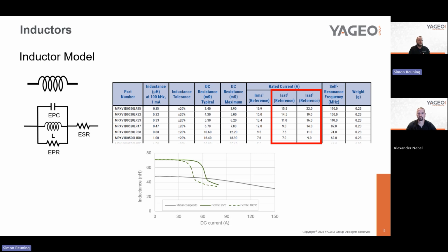And so now you're getting into the thermal runaway where you start getting hotter and hotter, and the inductance value is going to drop and you're running less efficient, and eventually something is going to blow up. So again, it is really important to consider the materials that you use for your inductors, because there's all kinds of different options available for you.